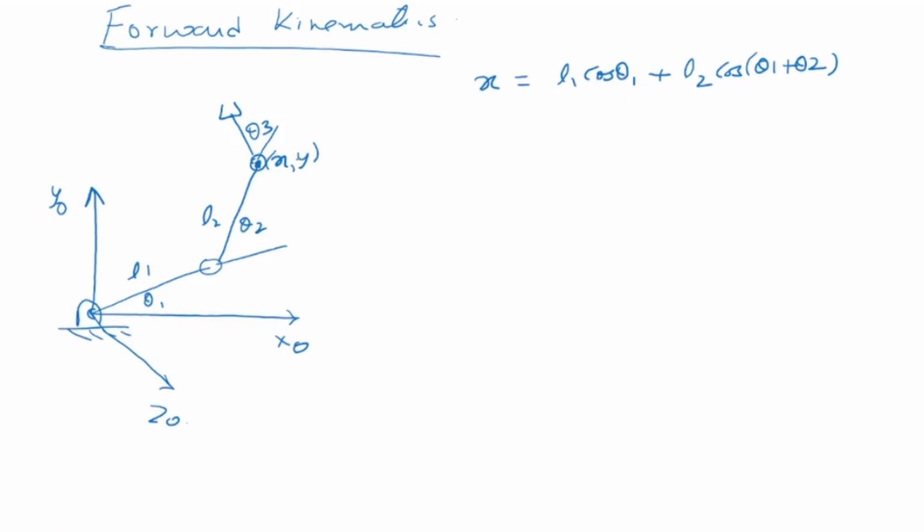So now we have this is my frame 3 and this is my XY. You can put your DH parameters and it will come to the same thing. This will become our X3 and this will become our third origin. So what about Y? I hope you're following how I'm writing these equations. My x1 is this much and x1 plus x2 is this one, so L1 cos theta 1 is this one, and L2 cos(theta 1 plus theta 2) is this one.